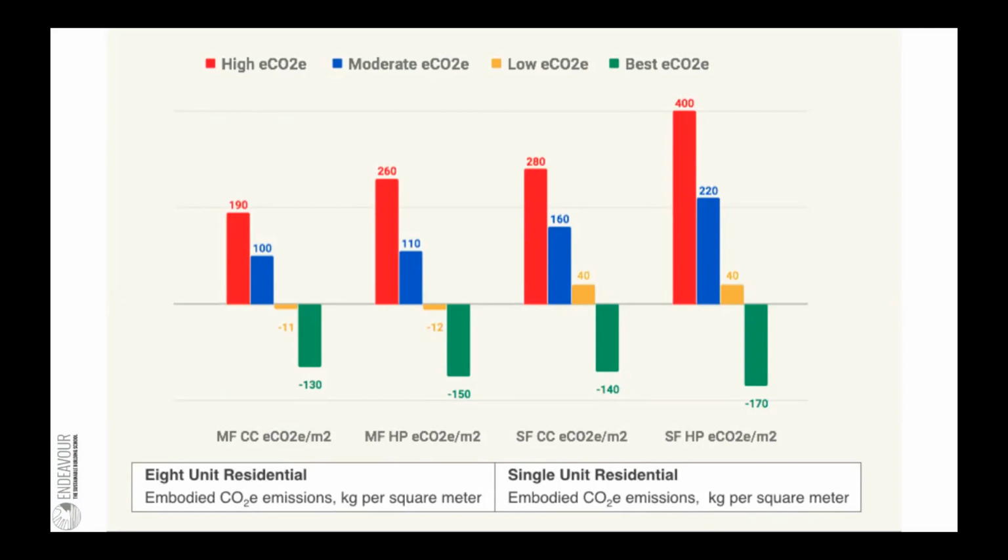The other interesting thing that comes out of this is even though the embodied carbon rises on the emitting models when the insulation level goes up, you can see that the storage levels also get bigger. So in some cases, if you're using emitting insulation materials, you're going to up your initial footprint.